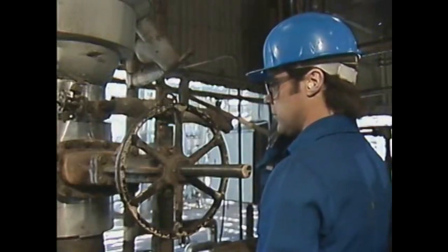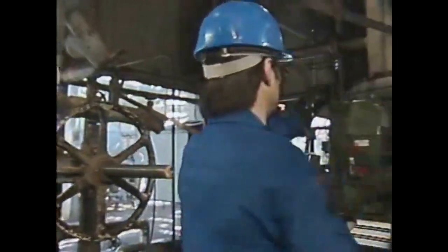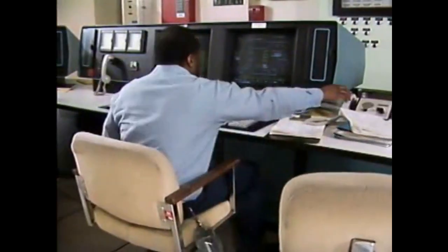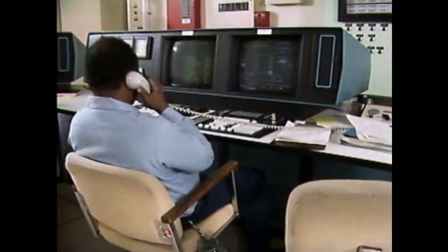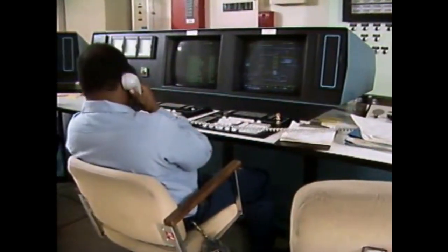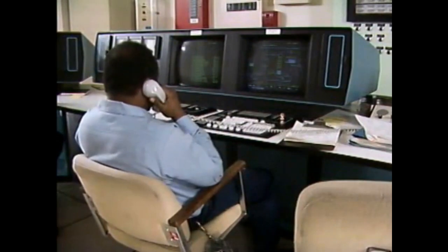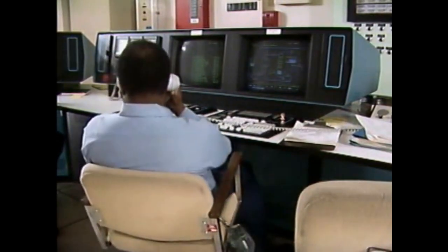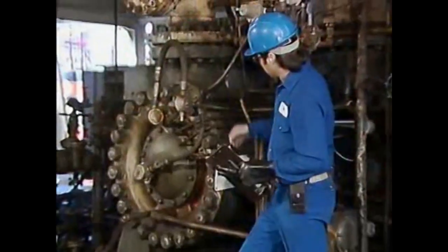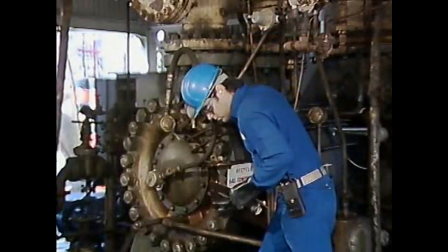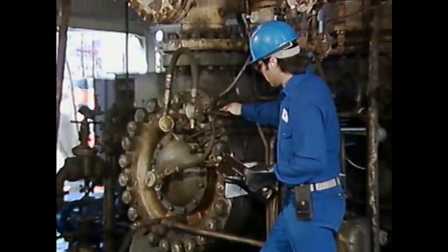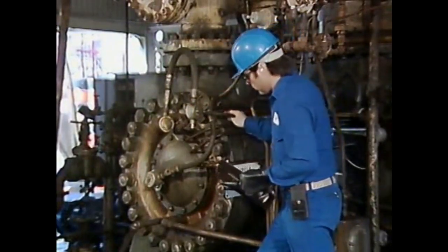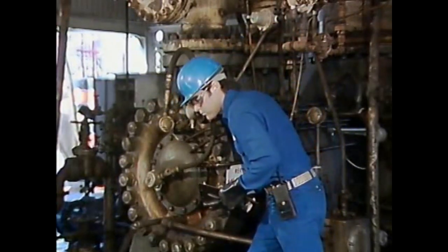After the critical speed is passed, the normal ramp rate is resumed. Some compressors have computer-based control systems. These systems often control ramp rates and make changes as needed to pass through critical speeds. Eventually, the compressor will be brought up to its minimum operating speed, which is the lowest speed the compressor can be operated at without causing surge or other operating problems.